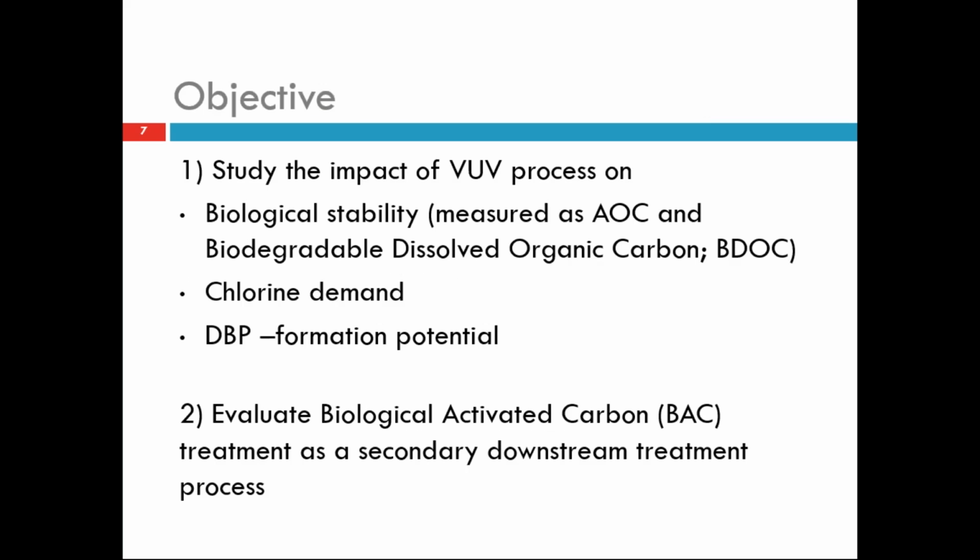Hence, the objective of our research is to study the impact of the vacuum UV process on biological stability, which is measured by AOC and BDOC. Biodegradable dissolved organic carbon is another parameter for biological stability assessment. And as the term suggests, it's the biodegradable component of DOC in the water.